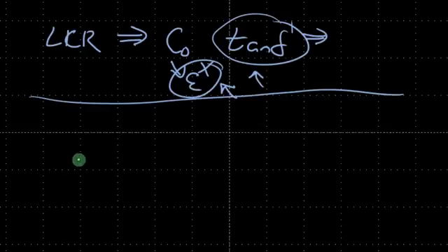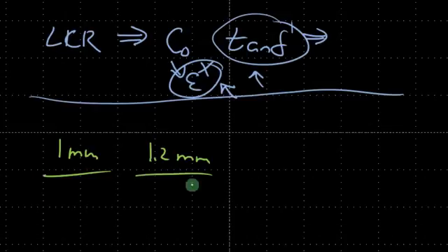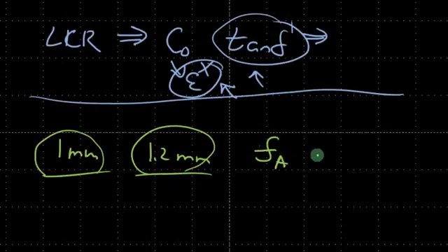So basically, I found out that he had varying thicknesses. He had 1 millimeter thickness, 1.2 millimeter thickness. And this would cause at least a 20% difference in the resonance frequency approximately. So immediately I said, look, you have to get the materials with the same thickness. That's the first step. To get the same resonance frequency, you need to use the same thickness. Okay? That's important.